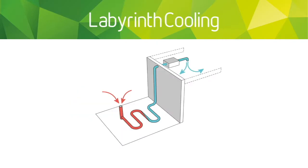Another sort of passive system, even though you're using a fan, is a Labyrinth Cooling system. It is actually quite good to connect it up to your MVHR unit. The one advantage of that is during the summer you get hot air, it gets cooled by the ground, and then you expel that cool air into the space. And then during the winter period it works in reverse. The cold air gets warmed up by the ground and then you expel it into the space.